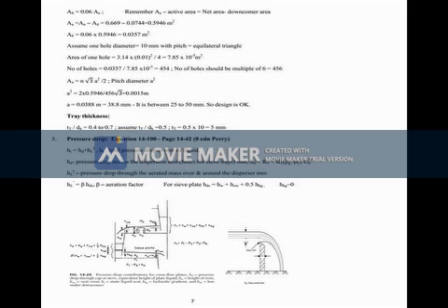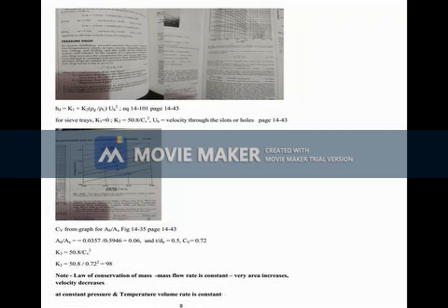Then draw the line AB dash with slope 2.5017. B dash is the point, where x1 is equal to 0.034. From the slope you can also find the amount of xn. So the amount of acetone in the exit water stream is 0.0234.